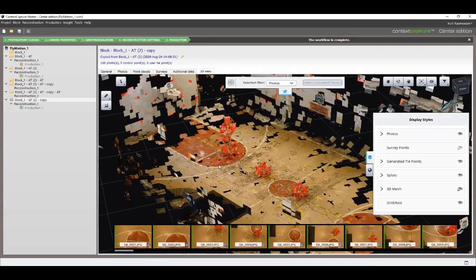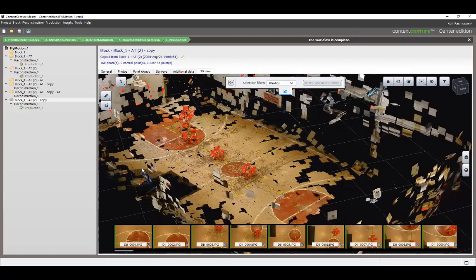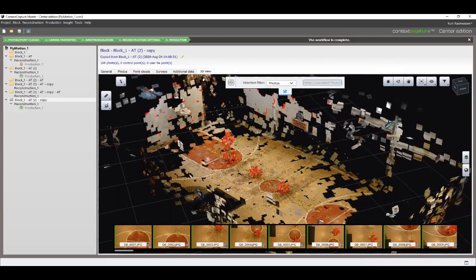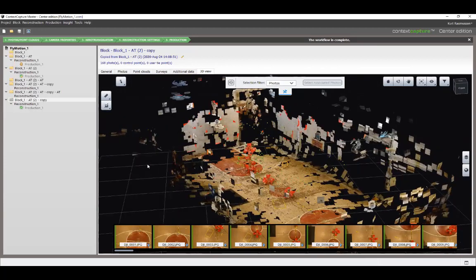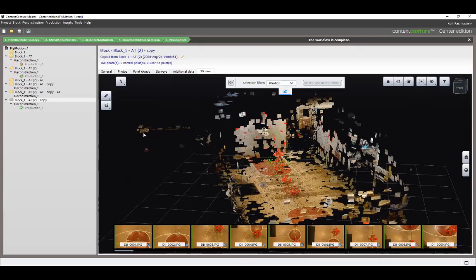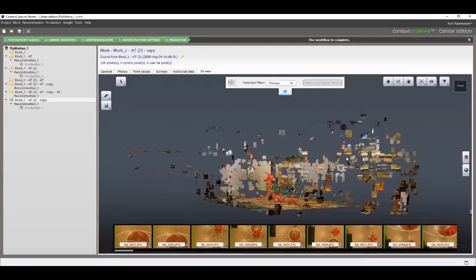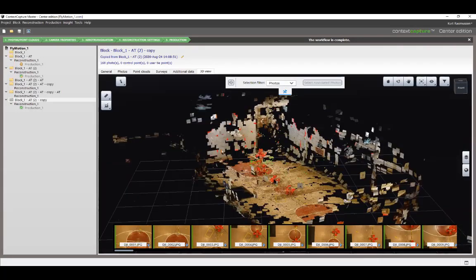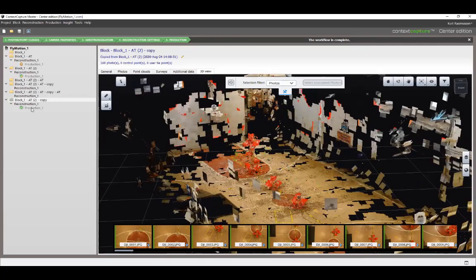And then I'll come back to the ground control points. So when we look at a model like this, right away, we first look at this AT result to see if there's any extra stuff that we have. Now, I know for this area, I'm seeing some stuff over here, some stuff up near the rooftop. So that's where I want to kind of address that.